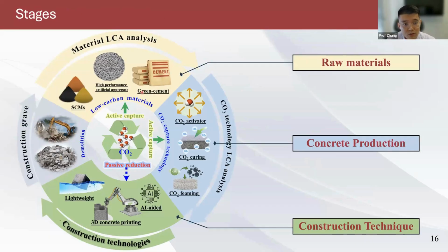We will also investigate different new SCMs generated from waste. Like I mentioned before, SCM is a material to replace cement. Artificial aggregates will be introduced, and different functional aggregates. We can achieve lightweight, thermal storage, and high strength using solid waste as a raw material.